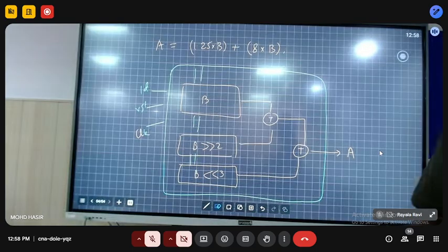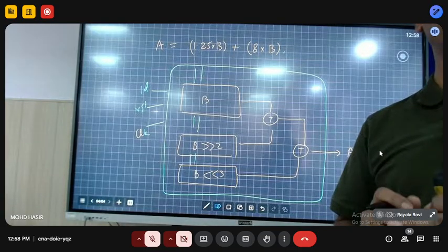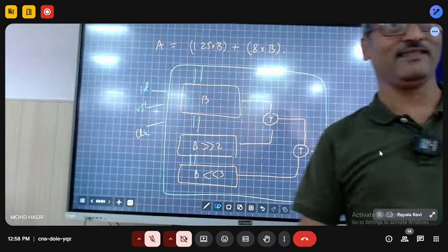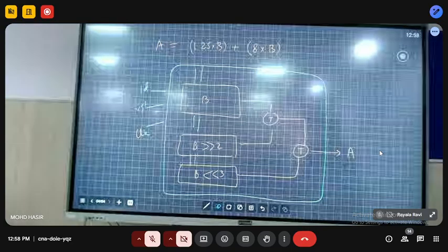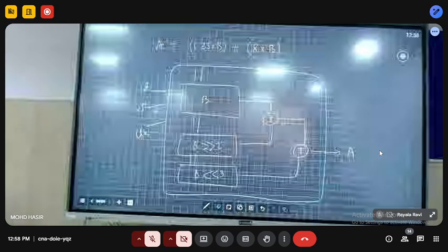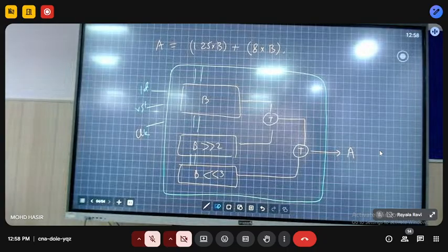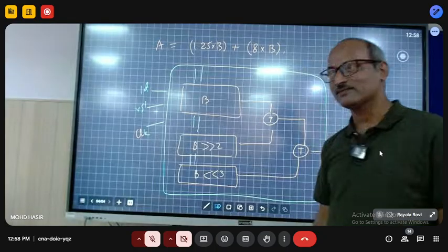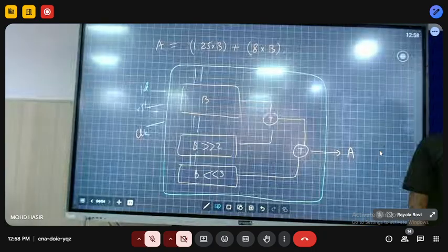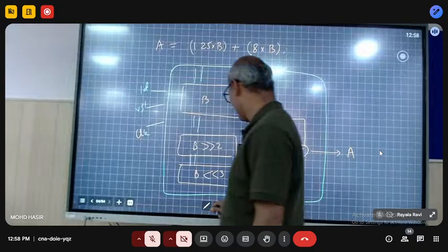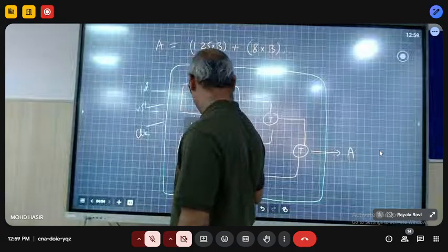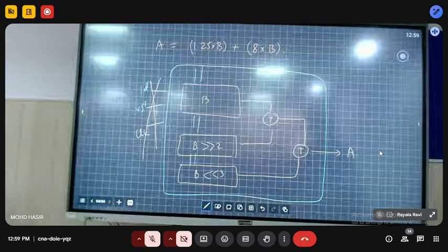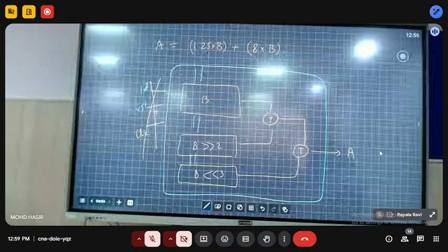So what is important? Another thing. See, why you need to have a rough idea: how many clocks will be required here? Two clocks. And while we are performing this rotation, I am completing this addition. Okay. And then in that result, I am using it. So this can be shared. Right? So, resource sharing. Okay. So plan your data flow appropriately.